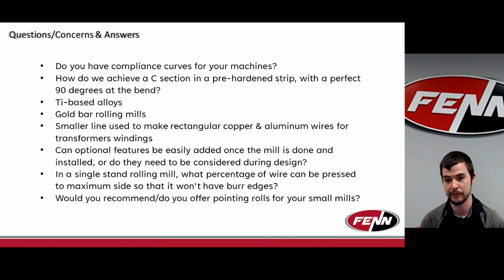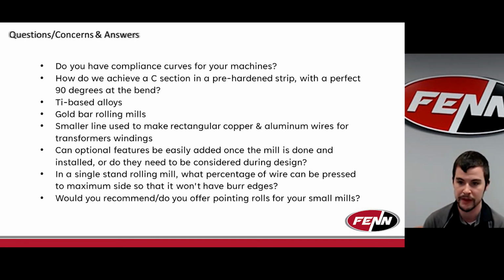Soft materials like aluminum and copper spread a lot more naturally, so that would assist a lot. But even so, with roughly a 24-to-1 width-to-thickness ratio starting from round, it's probably going to be around 4 stands to do the reduction work. You'd probably have your first 3 mills take very large hits to maximize spread, and then you'd use other types of roll tooling to clean up your width afterwards. There are definitely things I can assist with offline, giving some general calculations and working with people specifically on their pass schedules, at least on a surface level.